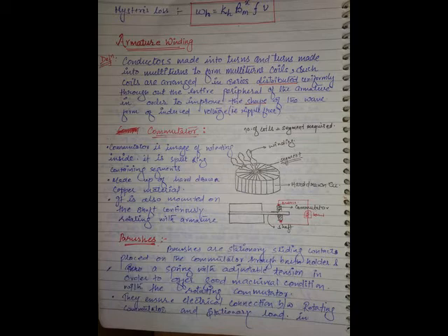How many coils? So total 10. Like that, if you make them, you connect them in series and you place them uniformly, distributed. All are connected in series only. If you distribute or if you concentrate, what is the voltage induced in both cases? Same. There is no change in the voltage, but you can think in this way.